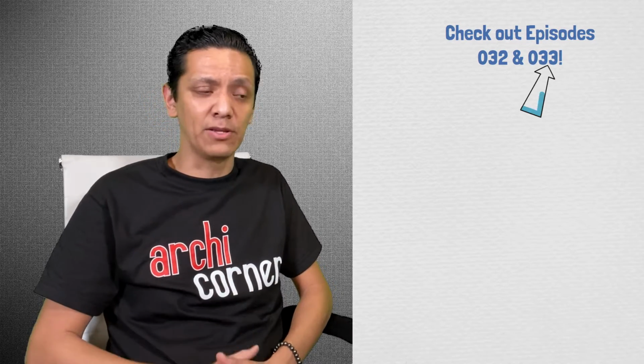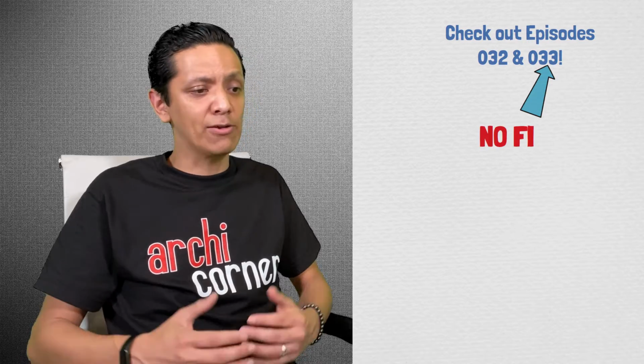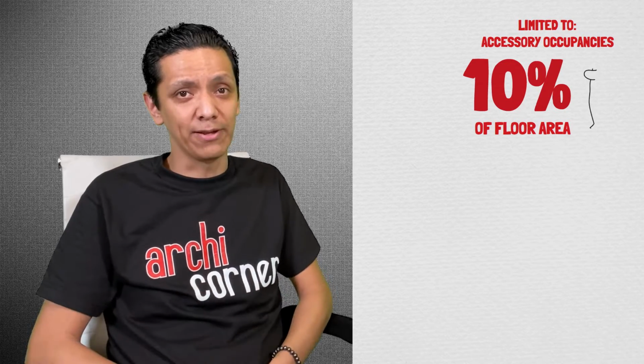Hello there. In our last couple of videos, episodes 32 and 33, we discussed the need for fire-rated separations between occupancy groups. In video 33, we talked about one of the exceptions that allows you not to provide that fire separation. But that was limited to accessory occupancies, which in turn are limited to 10% of the floor area.